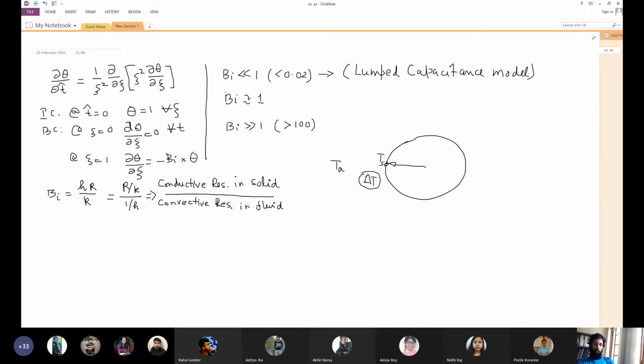So understand this point clearly. These are very fundamental concepts. This will come back again and again in various shapes and sizes. Steady state, unsteady state, all cases, there is an interface, heat is coming from one side and going through another medium, another phase. Whether it's steady state or unsteady state, something is coming and something is going. And if one side is more efficient than the other, the gradient on that side will always be much lesser. So that is the basic thing.